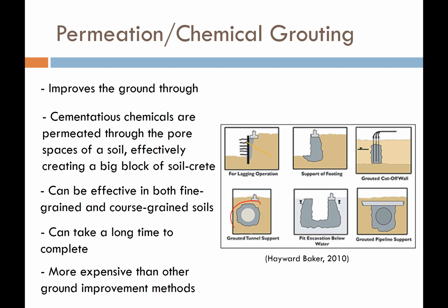We can use it to prevent seepage or strengthen the lining of a tunnel. I mean, there's all sorts of things we can do. Once you have this big tunnel of grout, it's easy for a tunneling machine to come and just bore a hole right through the middle of the grout. And then we don't have problems with flowing sands coming into our tunnel and flooding it.